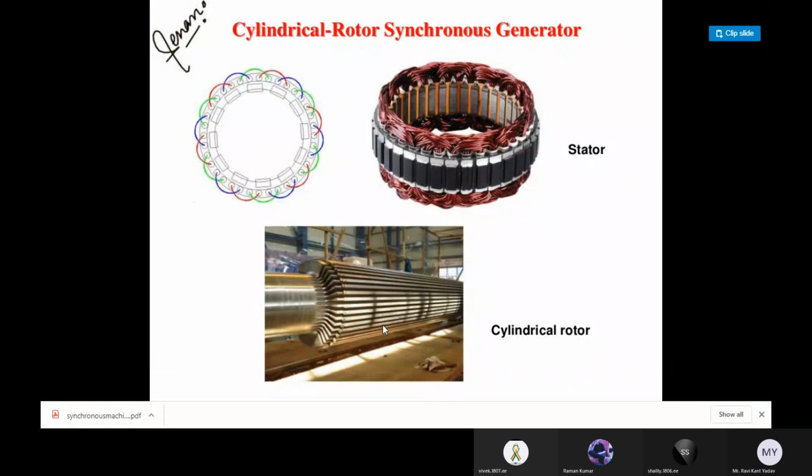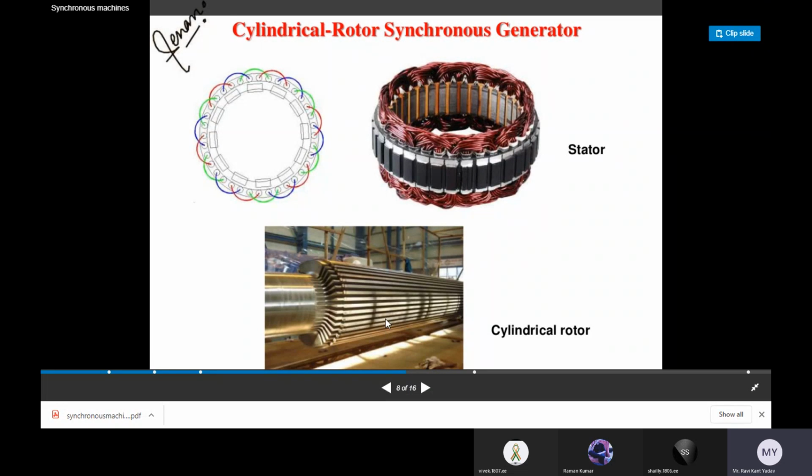If the magnetic field and coil are linked to each other, and the magnetic field is changing with respect to time, then the coil induces EMF. In this process, three-phase AC is generated in the stator winding of the synchronous machine. Okay? Are you getting it?